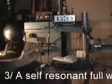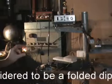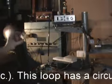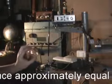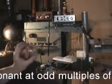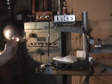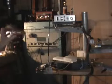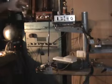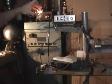3. A self-resonant full-wave loop antenna, which can be considered to be a folded dipole reformed into a circle or square, etc. This loop has a circumference approximately equal to one wavelength and will also be resonant at odd multiples of a wavelength. The loop can also be reformed into other shapes, such as coils, stars, or other configurations to reduce the surface area. Yes, this system also works.